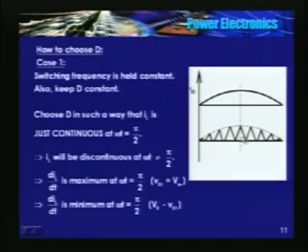So if the current is continuous near omega t is equal to pi by 2, it will be definitely discontinuous in other regions. Okay, because the maximum value of current decays slowly, but it becomes zero, just touches zero. If that is the case, when the current is minimum and dies down much faster, there has to be a zero current period before the switch is closed the next time. Okay.